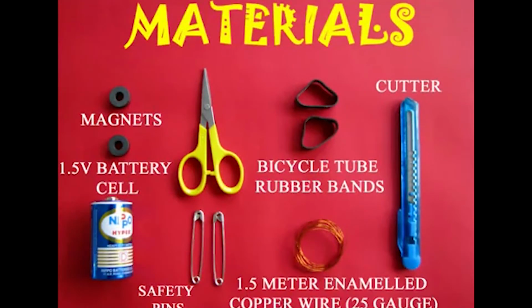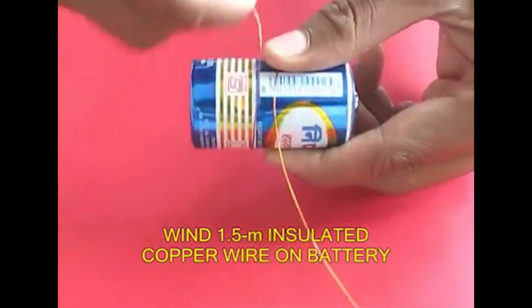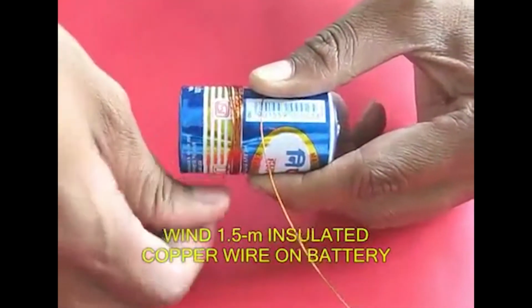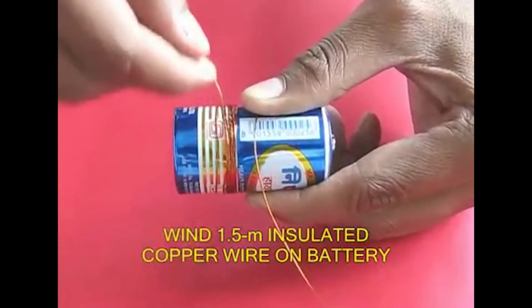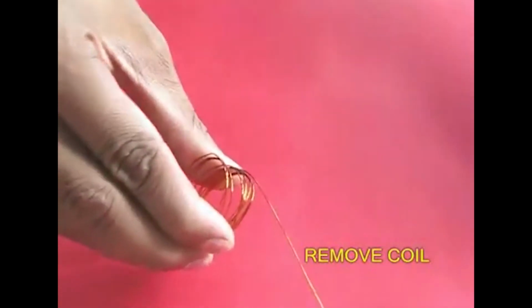In fact, you can also easily construct a motor using very simple objects. This is perhaps the simplest motor on earth. You will require some magnets, a battery, insulated copper wire, and some rubber bands. Take 1.5 meters of insulated copper wire and wind it round and round on a battery. There will be 10 or 12 turns, and then you remove the coil like a spring.